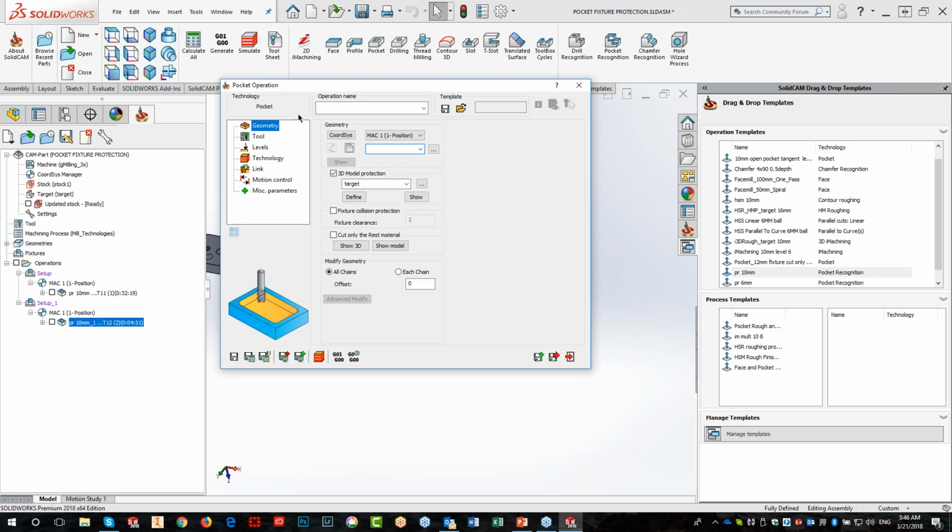Okay. And just for argument's sake, one nice thing with this drag and drop, for those of you that like to use 3D iMachining for your prismatic parts too, this works also very nicely. So drag and drop that 3D iMachining toolpath on there. You don't have to worry about those feeds and speeds on a 2.5D part. It also works out very slick. And if you guys behave yourselves, I'll even show it to you in a moment, what happens by drag and dropping a 3D iMachining operation onto a prismatic part.